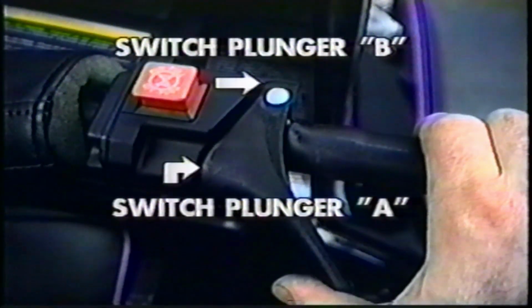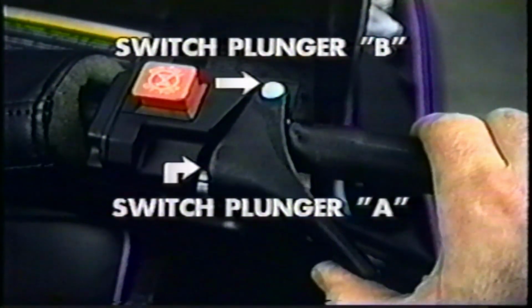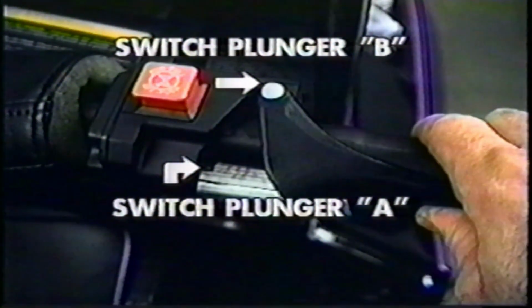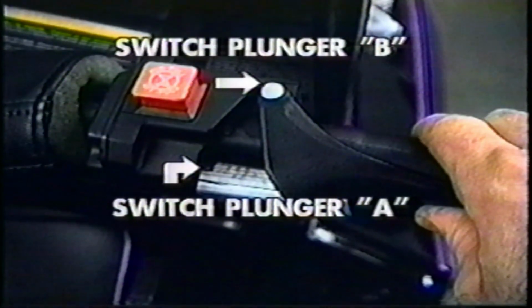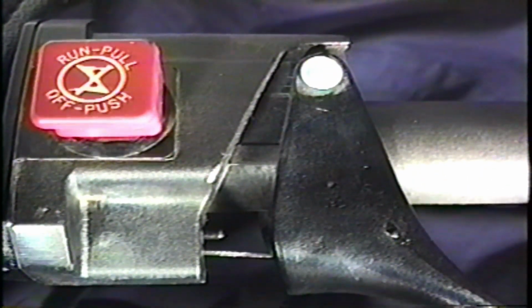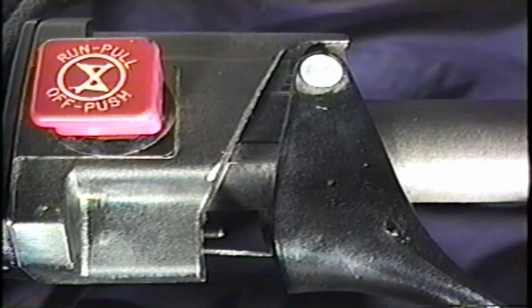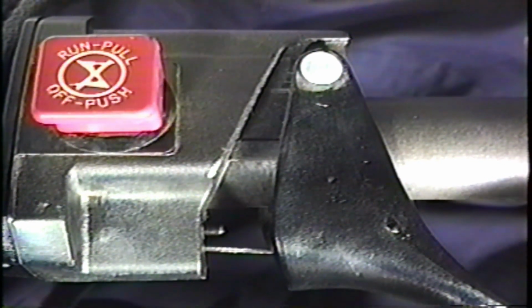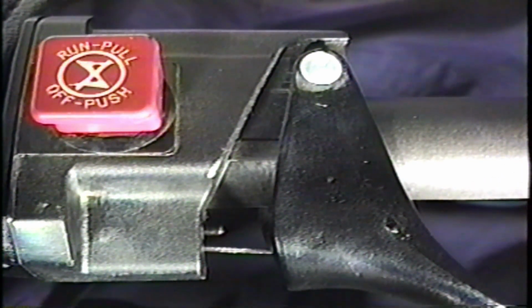When the throttle flipper is released, cable tension holds the throttle flipper against switch plunger A. The circuit is open, and the engine is allowed to run. When throttle is applied, pressure is applied to the lever pivot pin, which depresses switch plunger B. The circuit is still open, even though the contacts of switch A have closed. In the event of a malfunction, cable tension is lost, causing both switch plungers to remain outward, completing the circuit and grounding the black CDI wire, preventing ignition spark.